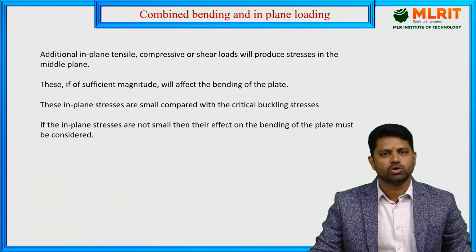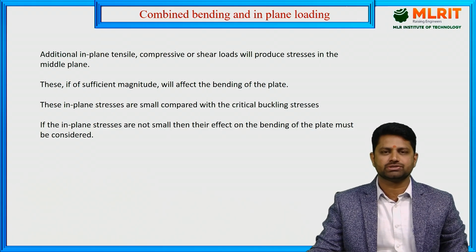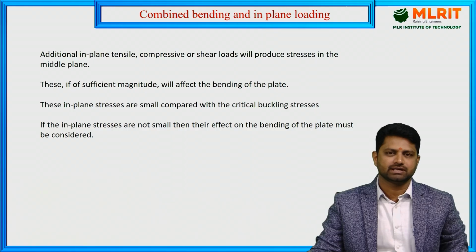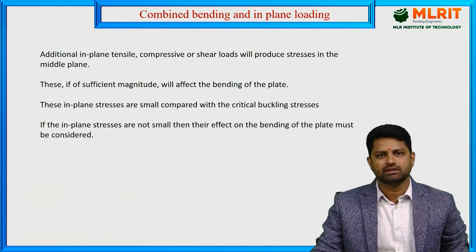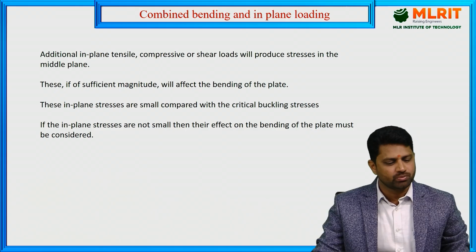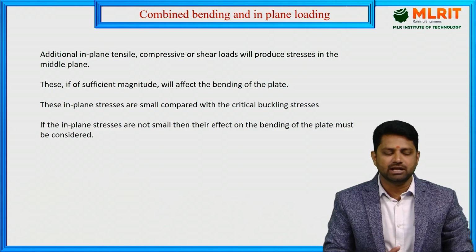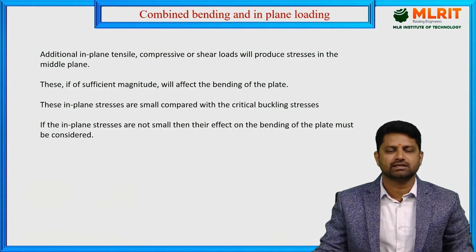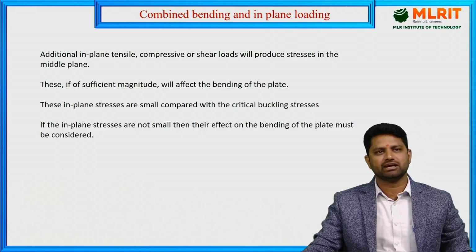Additional in-plane tensile, compressive or shear loads produce stresses in the middle plane, and we know clearly that about the neutral axis or neutral plane there exists no tension and no compression. These additional in-plane loads produce stresses even in the middle plane, and if they are of sufficient magnitude, they are going to affect the bending of the plate.